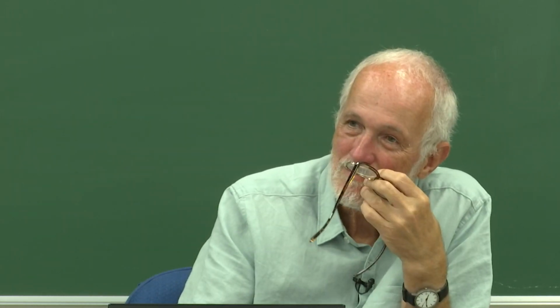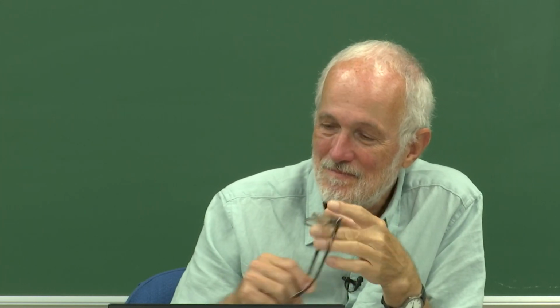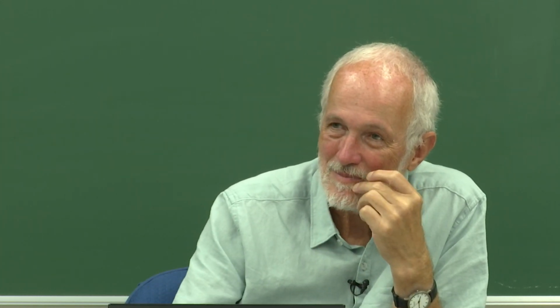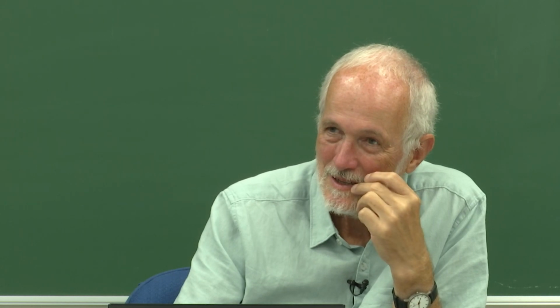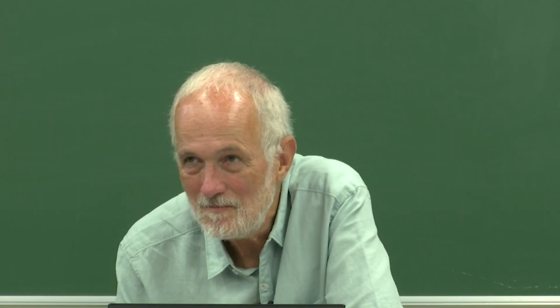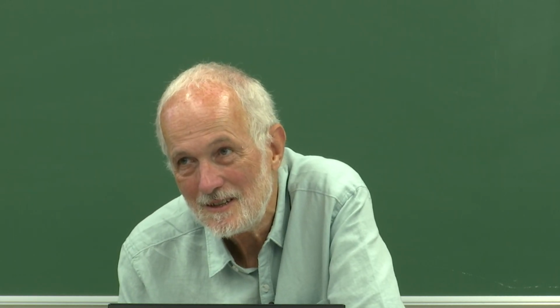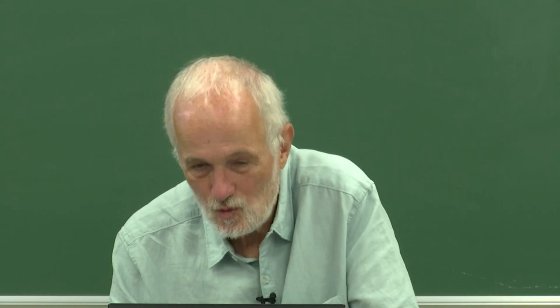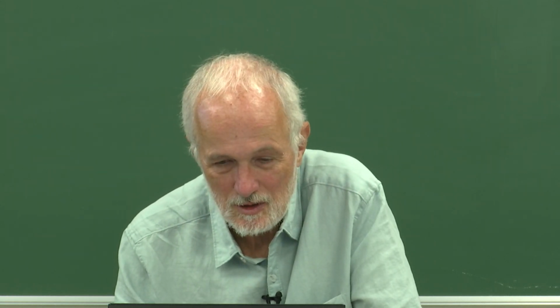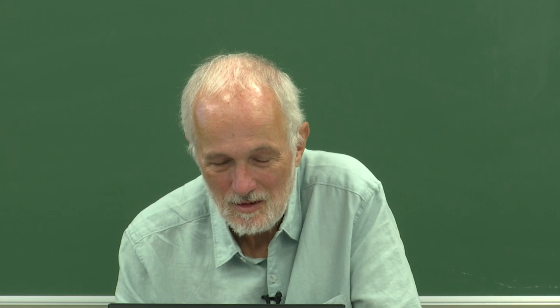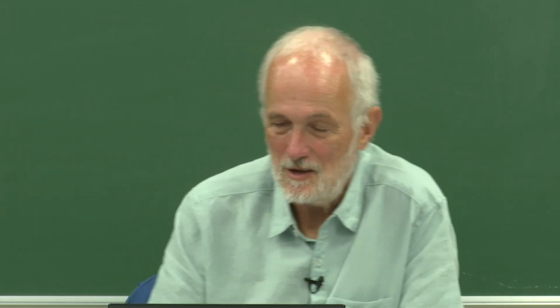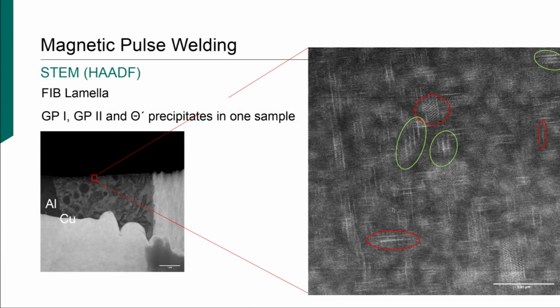The GP zone you have mentioned here, from structure-wise can we differentiate between them, or something extra? GP zone 1, 2 and theta prime, so that is distinguished between them according to their structure only? Right. If you go back to the slide here, I think here it's best seen. These phases all have this characteristic structure of 1 copper layer, 3 aluminum layers, 1 copper layer.